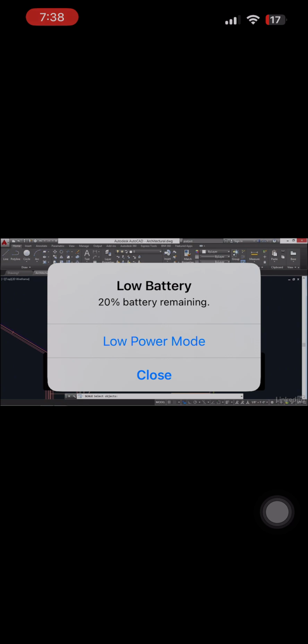Scale this object, enter, and this time I'll scale it more or less from the middle of the table. And you can see what's happening there. It's getting bigger or smaller relative to that base point. So I'd like to make it 150% larger, and so the scale factor would be 1.5.